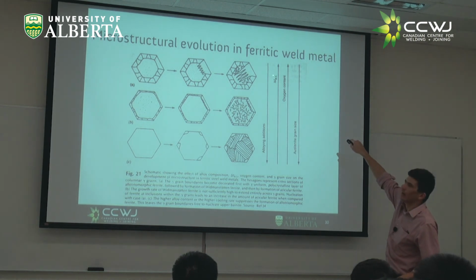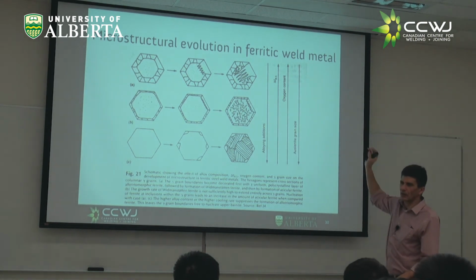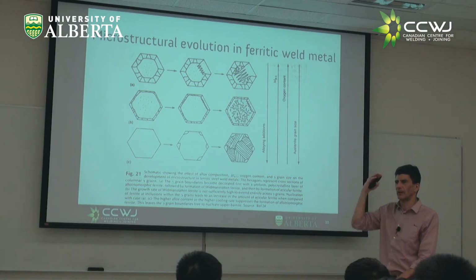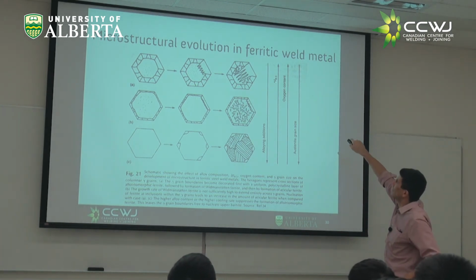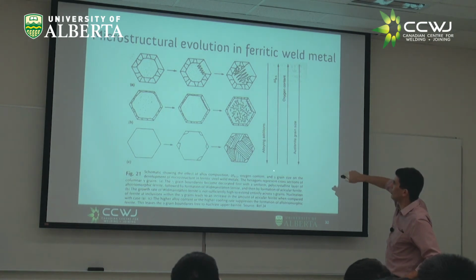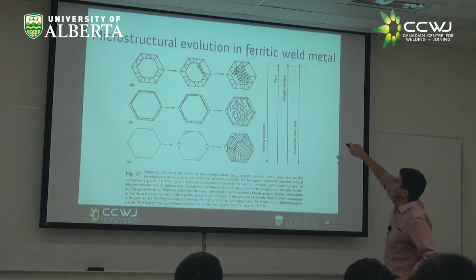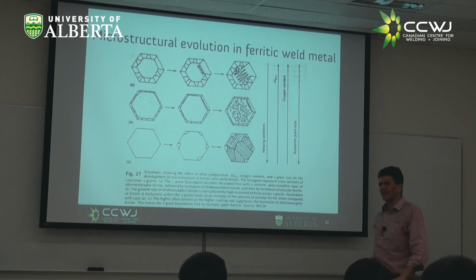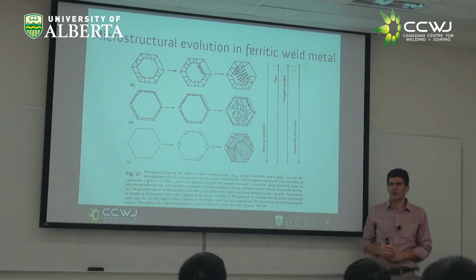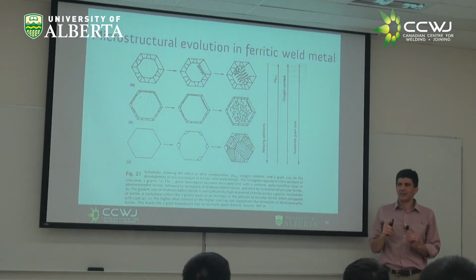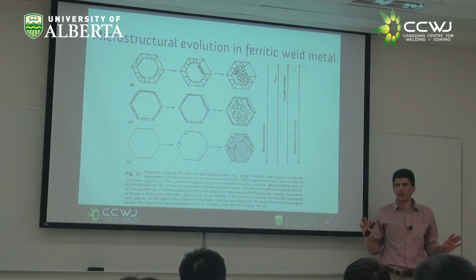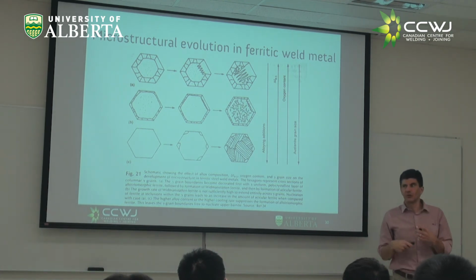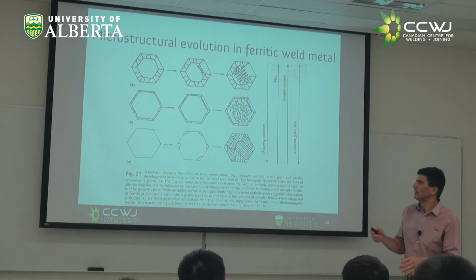Here we have the T85, which you already heard about, right? Like the time to cool from 800 degrees to 500 degrees. So essentially this is long times to cool or fast cooling rates. And here's oxygen content. Funny, right? Who cares about oxygen? But the oxygen is tied in the inclusions. So if you have no oxygen at all, you would not have inclusions and you would not be nucleating some components.